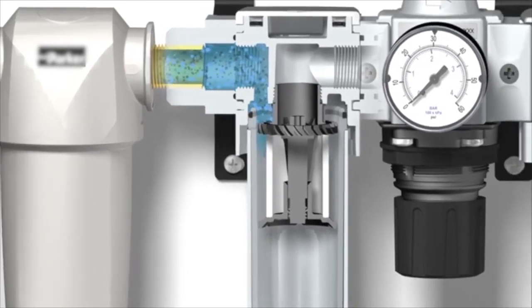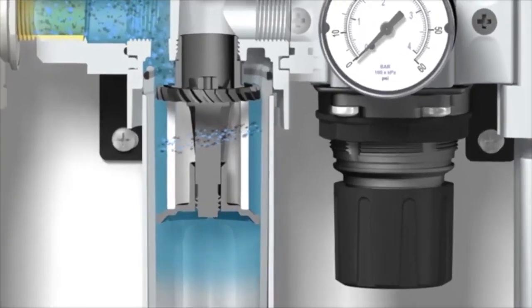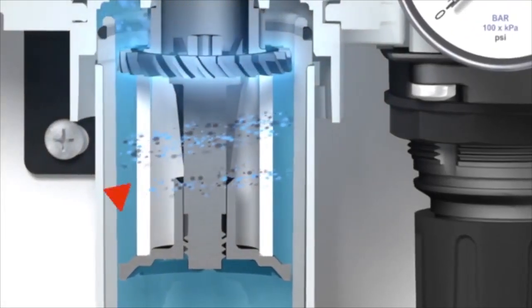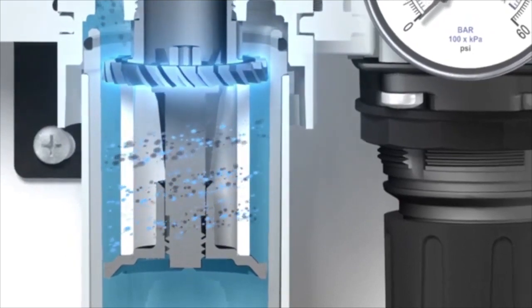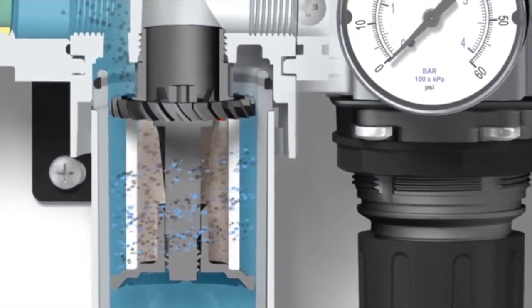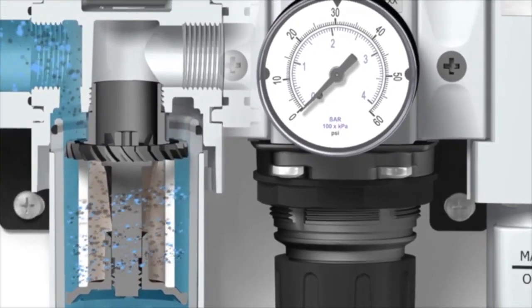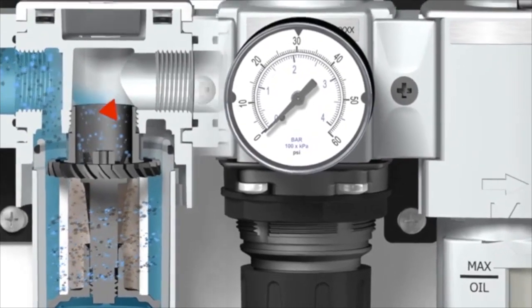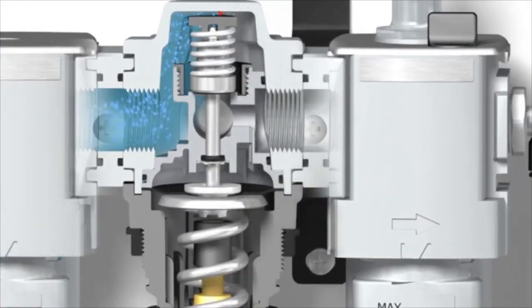The next unit is a filter, which further removes particulate and moisture in a 2-stage process. Just like in the bulk liquid separator, a series of vanes or louvers in the filter circulates the air in the first stage. In the second stage, the air passes through a screen of sorts, called an element, in order to catch unwanted debris. Once dried and cleaned, it is common to adjust the level of air pressure coming out of the compressor. This adjustment has an impact on how much force the system generates.